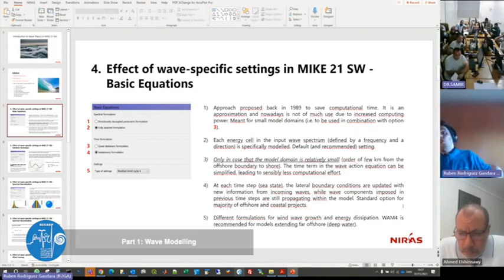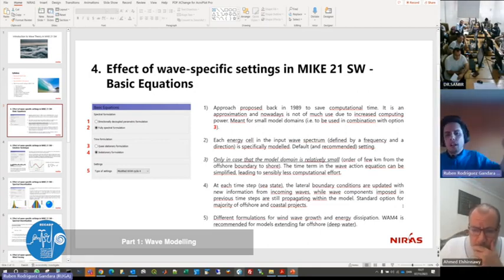Now you take a look at your boundary conditions, and you're telling me, okay, my model is going to be fed with new boundary conditions every hour. Let's say that you have a time series of hours with values on the hours. And then you can say in this case, okay, for my smallest wave, it only takes half an hour to travel the entire domain.